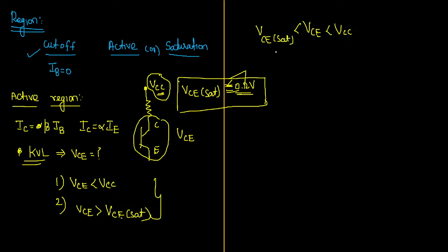See, only if the transistor is in saturation region should 0.2 come. If it is greater than 0.2, it means it is not in saturation region. So simply what you can write as your answer is: transistor will be in active region only, sir. No issues with this.